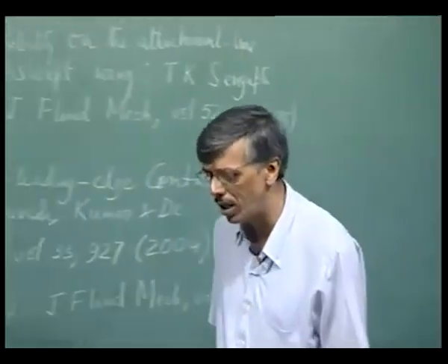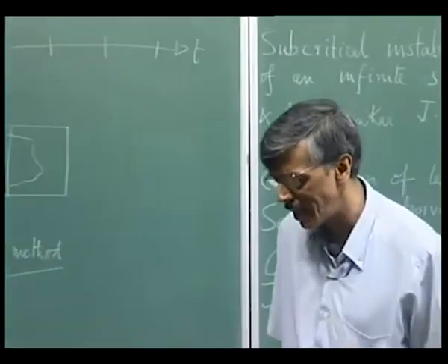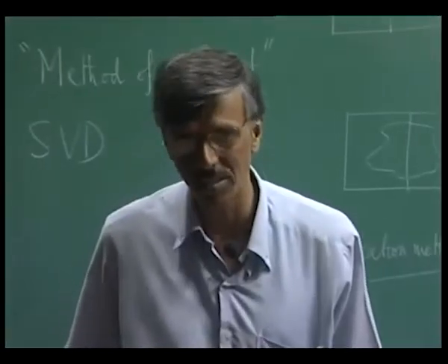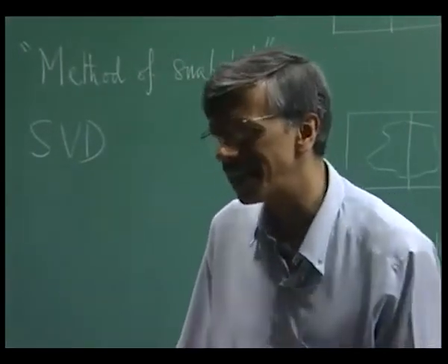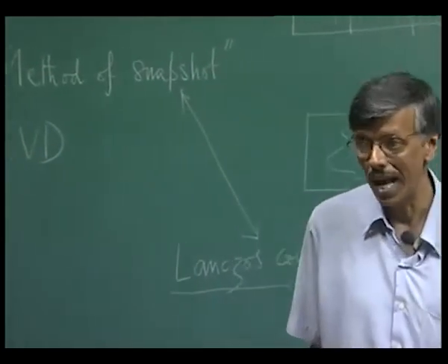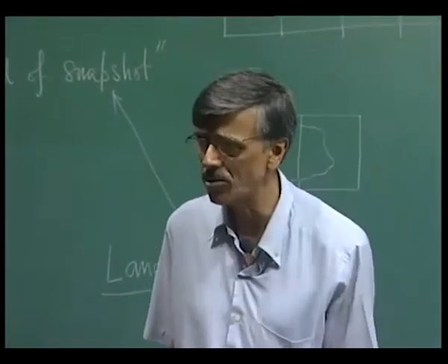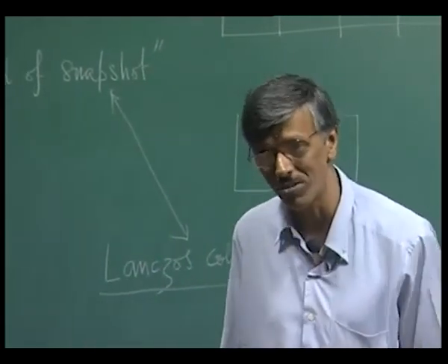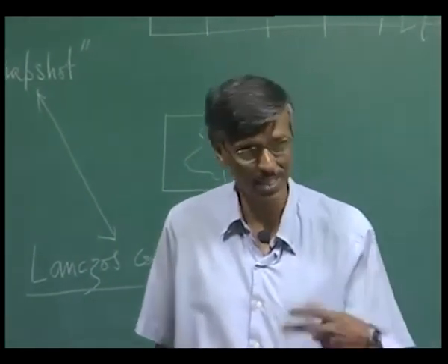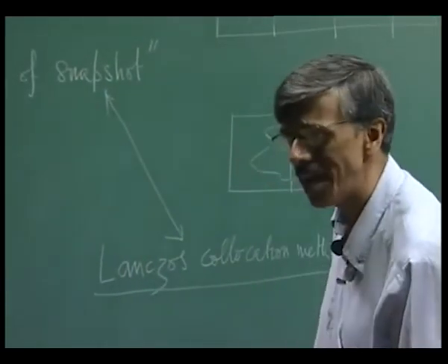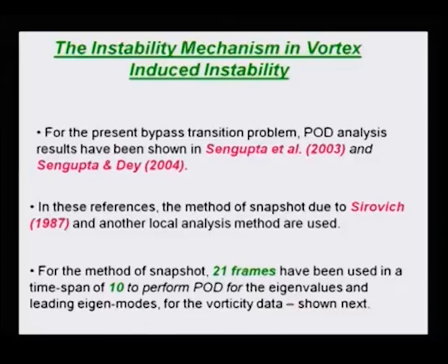If you are looking at the disturbance velocity field, then those eigenvalues represent kinetic energy of the disturbance field. If you are looking at the disturbance vorticity, then you are looking at the disturbance entropy, right. So, we can take both these routes. However, we realize that vorticity dynamics is more central in understanding fluid dynamics.